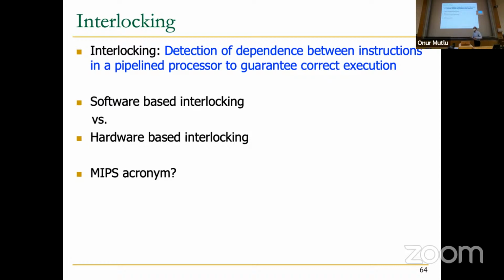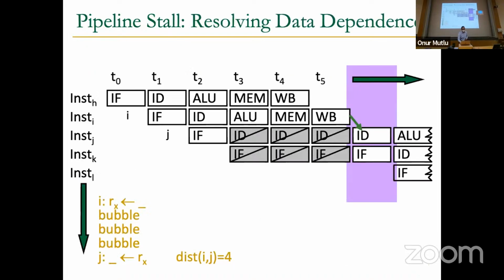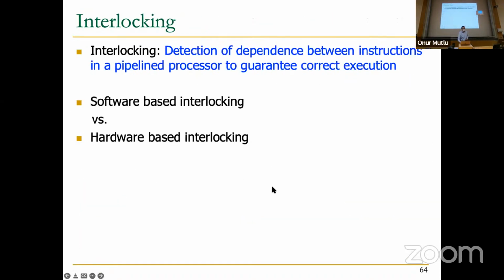So, microprocessor without interlocking pipeline stages, because you may not have heard that. Basically, that was their goal. When these people designed the MIPS ISA, their philosophy was that hardware is going to be extremely simple. We're going to put all the burden on software because we believe that we can do a good job in the software. And the hardware is going to be simple and fast, hopefully. It's going to be the responsibility of the software to detect the data dependencies and make sure wrong things don't happen in the pipeline. That's what they said, basically. This ISA is designed to be a producer of microprocessors without interlocking pipeline stages, meaning without hardware interlocking.